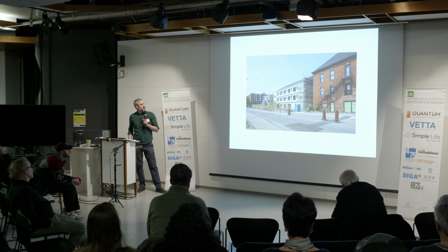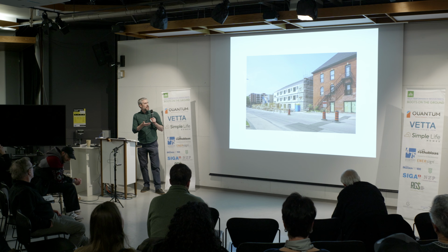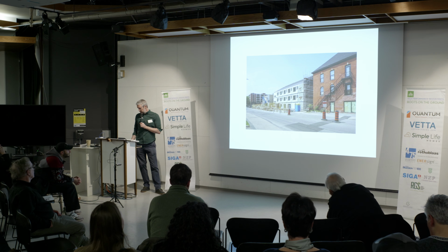delivery. This is an image on site then, after the modules were stacked, so you can see these spaces that were generated in between to allow the structural interconnection, and then we had to lap the membranes over the top. The pitched roof was actually entirely site-built, modular in its own right in that we used prefabricated wood trusses, but not full volumetric modular.